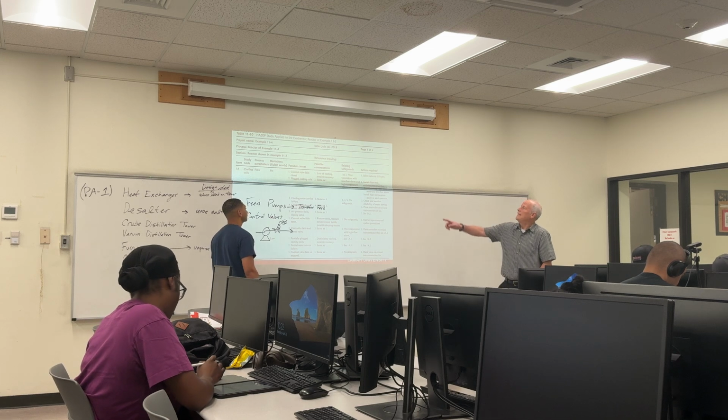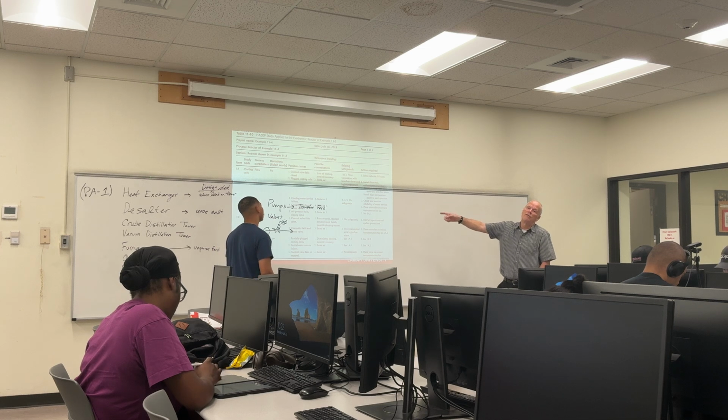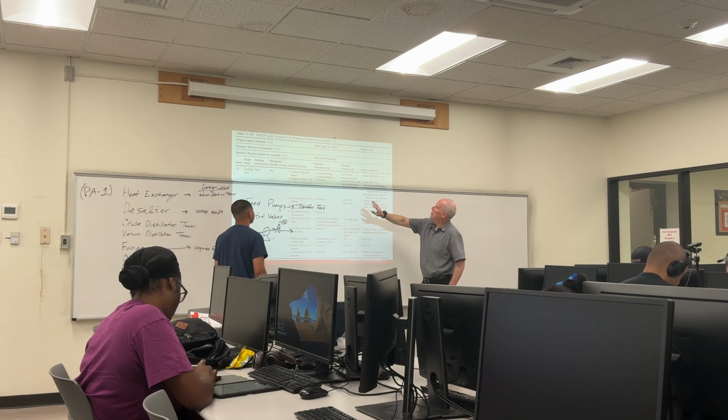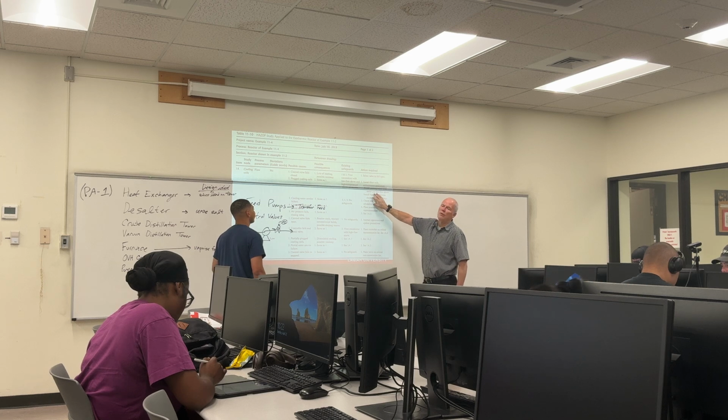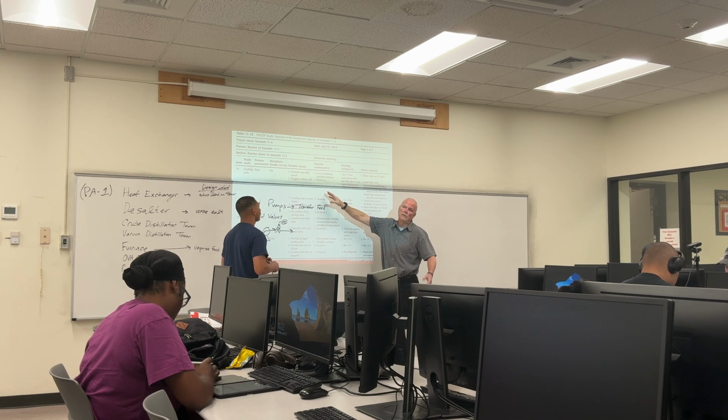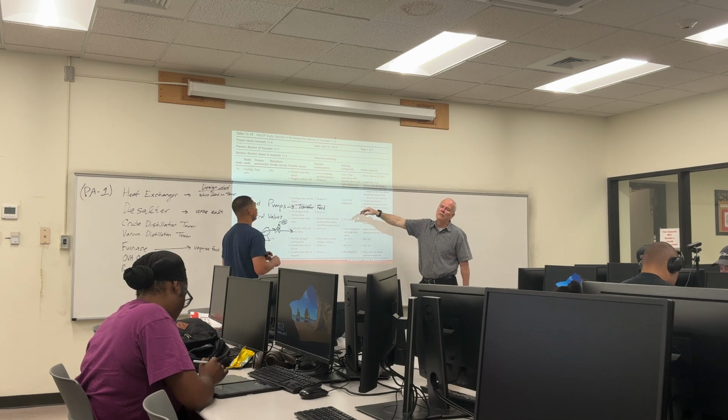So the existing safeguard may be a low flow alarm, just like what they said for this reactor. Okay? So that gives you a safeguard or two. Action required, you can come up with that, but it gives you the consequence, because the consequence was your crude furnace is burning down.